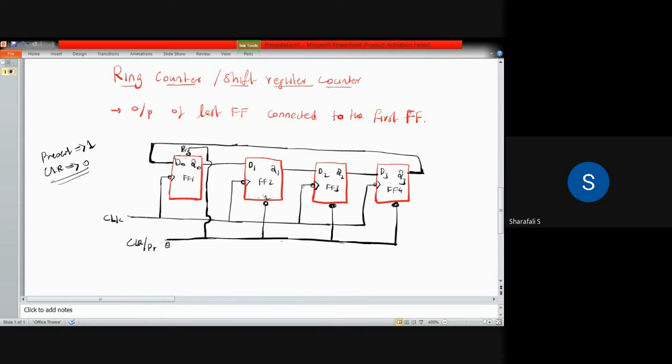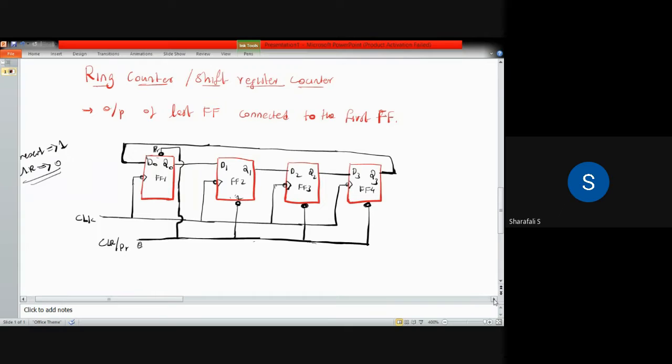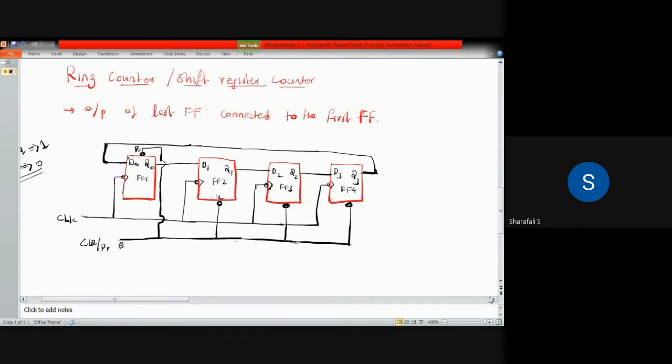That's why we are putting a dot here, because we have to take note of that particular binary value, or the complement of that binary value. Now, when you are considering this preset, first we have to consider the preset and the clear state. So we will clear all the values in these 3 flip-flops.